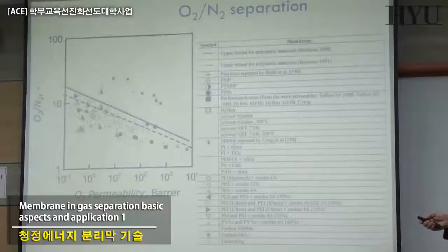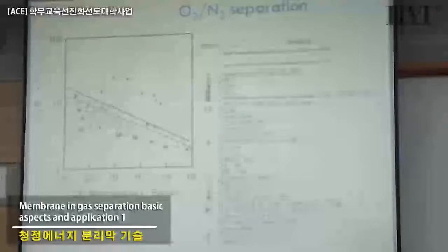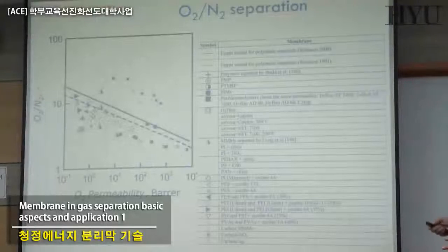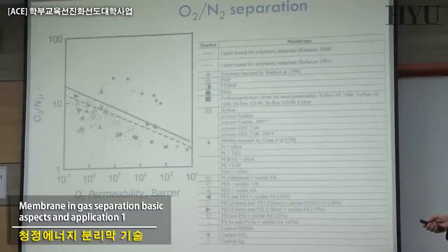and you can see here the kind of behavior. You can also have all these points here, which are materials that are not traditional polymers. It's not just this polyimide, etc., but systems where there is zeolite together with polyether sulfone or some Teflon, which is a traditional new fluoropolymer with specific properties, and the Robeson plot basically is observed at the highest separation factor.